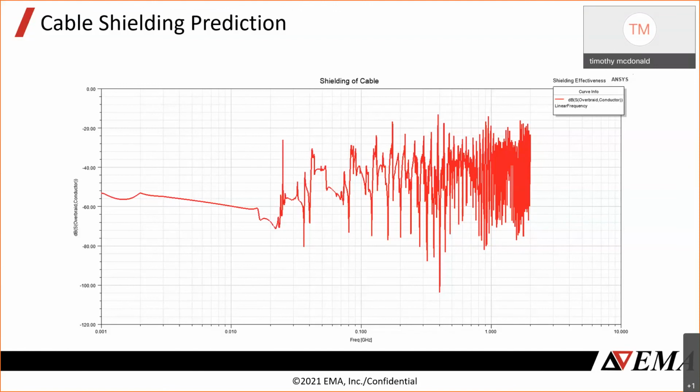You could do it CW frequency by frequency, but the recommended way in an EMA3D time domain simulation is to use a transfer function method where we can use a very short pulse in the time domain that has all the frequencies, and by careful use of transfer functions, we can extract our CW results for both susceptibility or emission. So yes, usually since we're doing EMI/EMC, we're comparing to those CW cases.